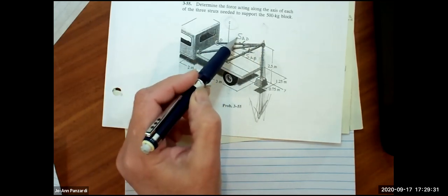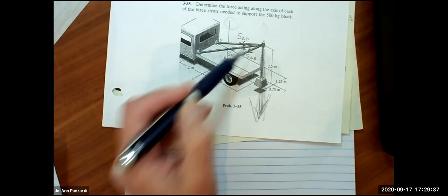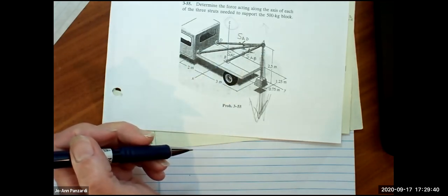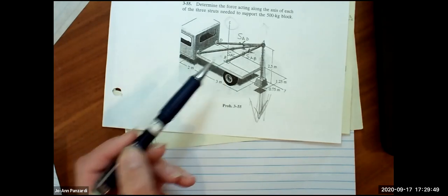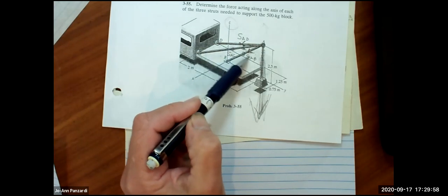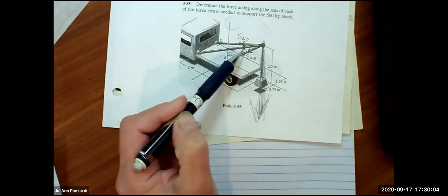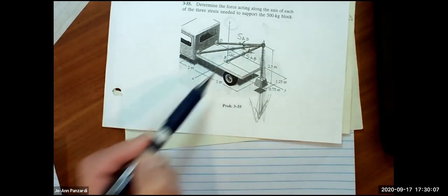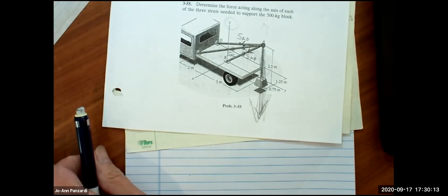So what does that mean you're going to get? What values are you going to get for these struts? At least one of them is going to have a negative, to show that it's actually going up. We could take a guess, and Isaac said he thinks it's this one, but we'll check it out and see. They're not all going to be the same. I'm trying to get you into the sign convention of drawing things when you don't know which way they're going. Draw them so that you're drawing them in tension. And then if you get a negative answer, you know it's compression and it's actually going in the other direction.